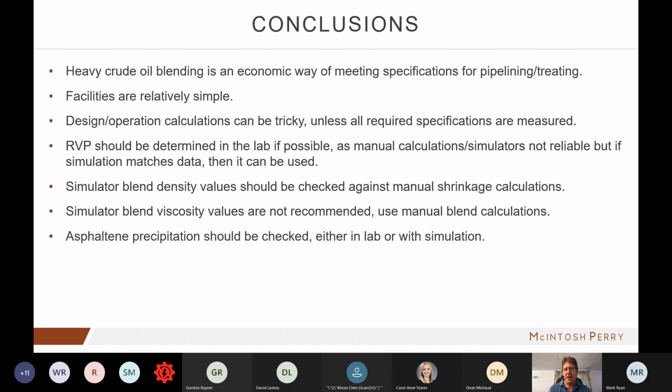For example, I dealt with somebody recently that blew a tank roof off because they overblended, and then there ended up being a tremendous amount of vaporization, and they were not at all concerned about vapor pressure in this particular instance, and probably should have been. Talking to them later, they're also having problems with their pumps, so it's likely overblending.